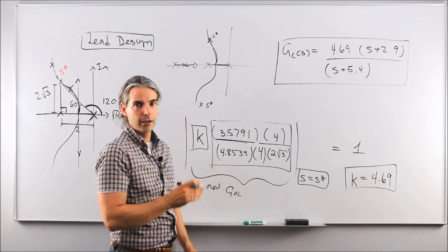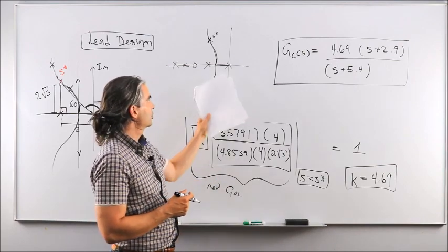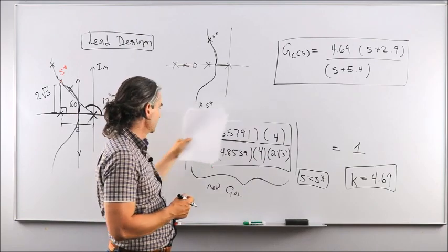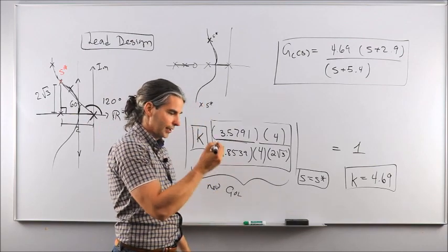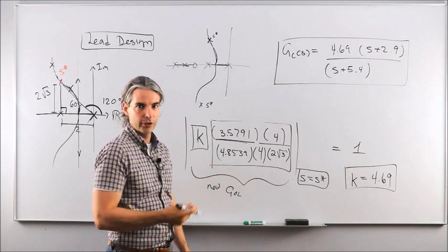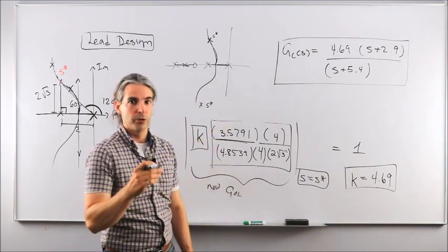Okay, got this. And the last part is just to figure out how much gain you need with the magnitude condition, just by measuring the respective distance between each individual poles and zeros you have in the new open loop transfer function with respect to the desired pole location.